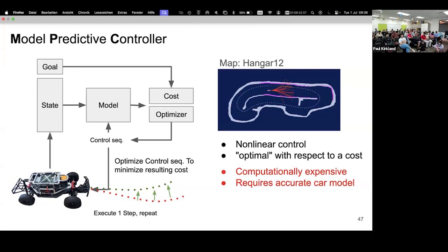Also we have, as in the car, very tight integration with physical robots, so that the same controller you deploy in simulation can be automatically uploaded to the physical cart pole, and mostly works. There is still some simulation-reality gap, so not every controller which works in simulation works on a physical cart pole, but generally, as much as possible, we try to calibrate this simulation to adjust it towards this particular robot.